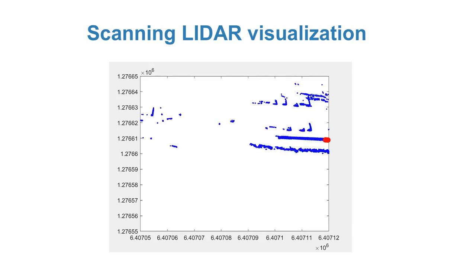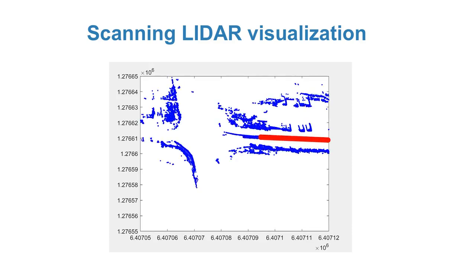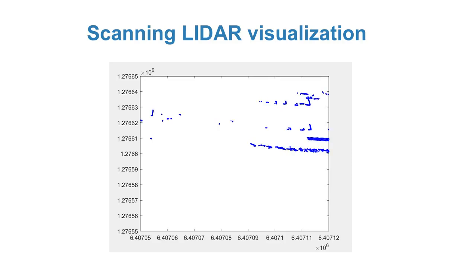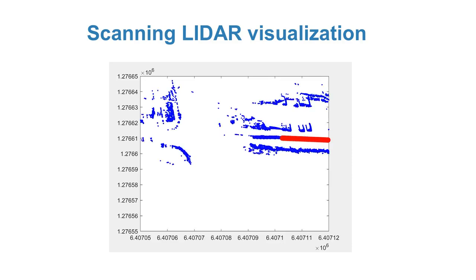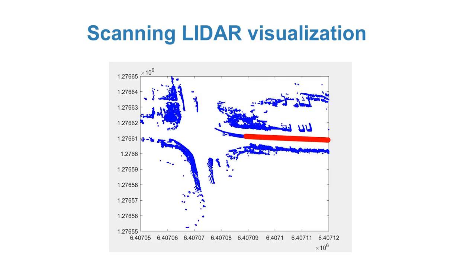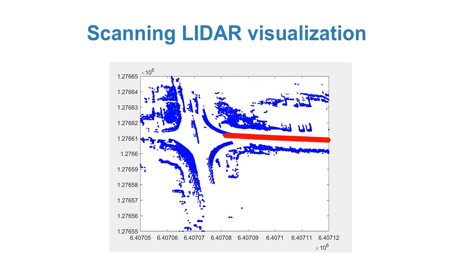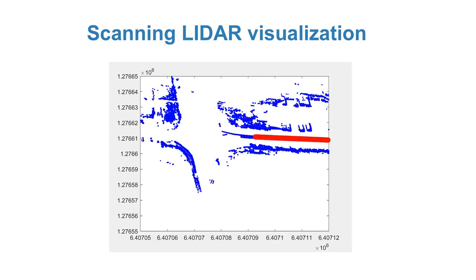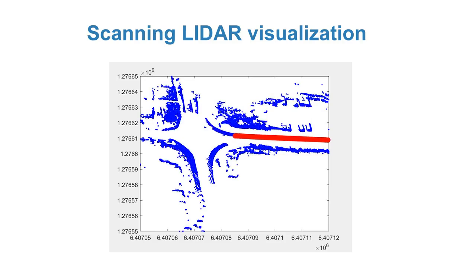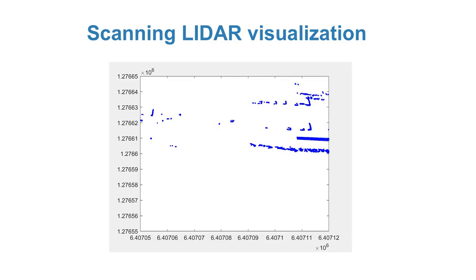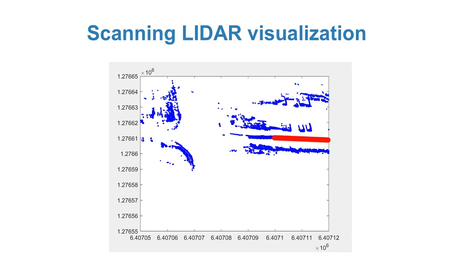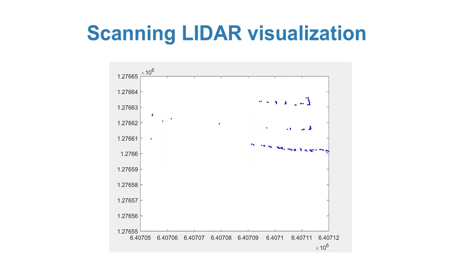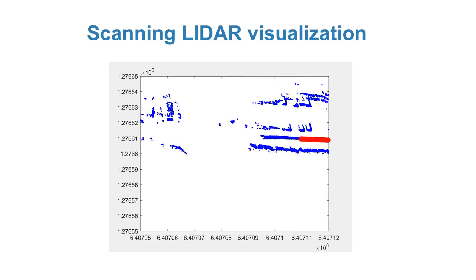Here you see an example visualization of a one vertical layer LiDAR sweep from an old homemade LiDAR unit. The red dot is the own vehicle as it moves. As time goes, the vehicle is moving towards the left, making a trail of red dots. The blue dots are the LiDAR measurements plotted in global coordinates over time. That is, 20 times a second, approximately 250 data points are measured, with approximately 1 degree horizontal separation, covering approximately 190 degrees in front of the vehicle.